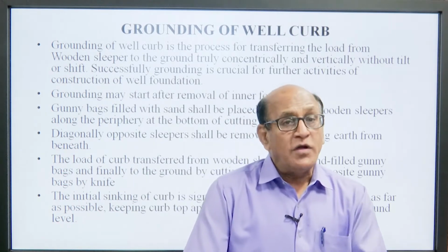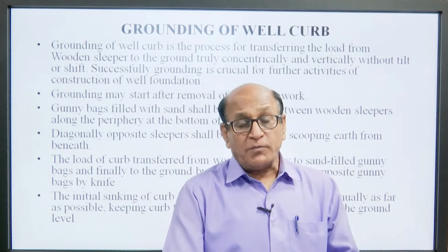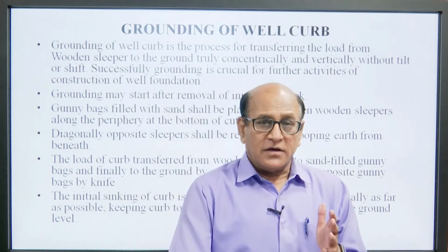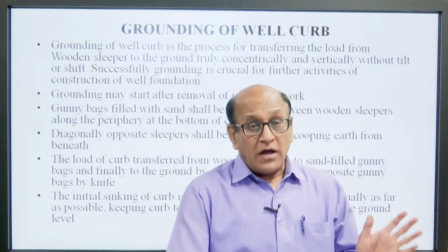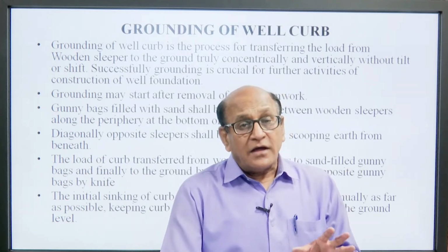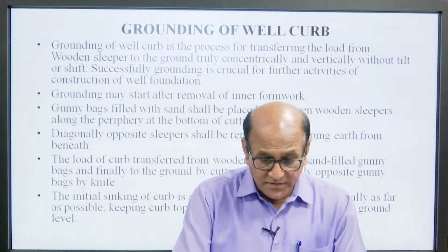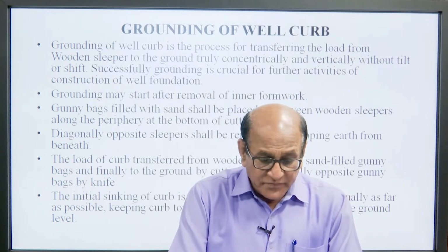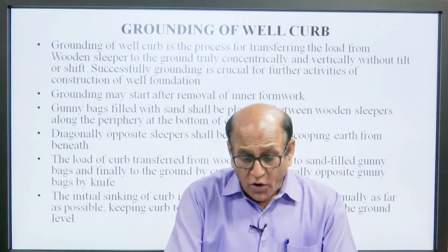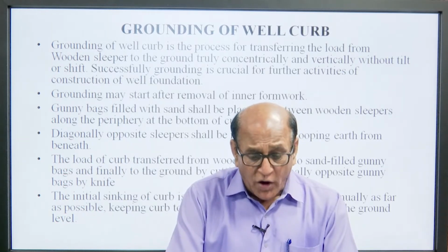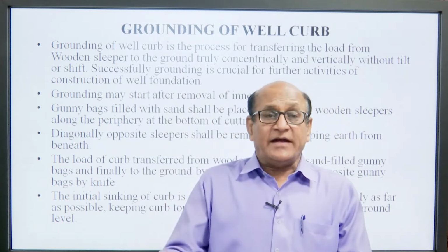First of all, we will remove inner formwork. Before starting our work, first of all we have prepared inner formwork, then we prepared outer formwork. For the removal, again inner formwork is removed first. Gunny bags filled with sand shall be placed between the wooden sleepers along the periphery of the bottom of the cutting edge. Means in between the sleepers, gunny bags filled with sand will be placed.